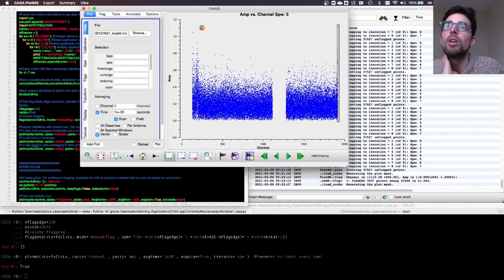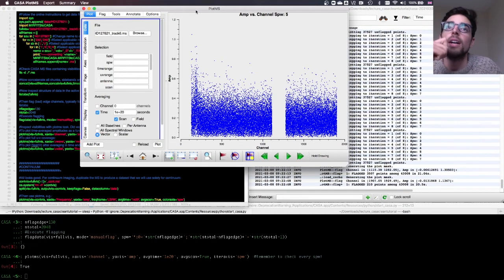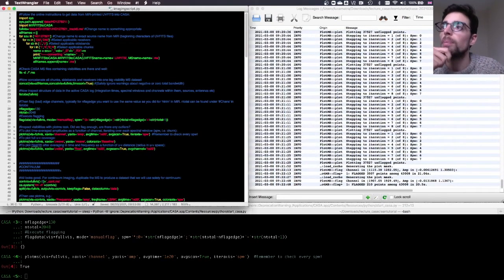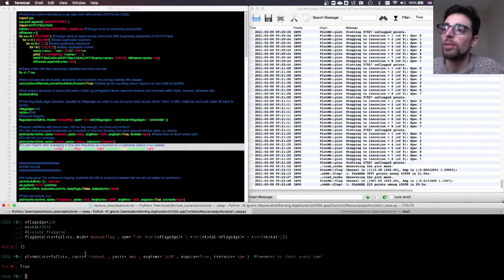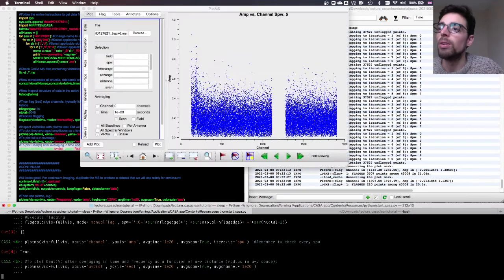Now, the next thing we're going to do is use plot_ms, but to plot something that we've seen in my non-imaging analysis lecture. We're going to close this now. We're going to plot using plot_ms. Now, instead of amplitude versus channel, here we're going to plot the real part of the visibilities as a function of UV distance. So that's again the radial plot in UV space that I talked about in my non-imaging lecture. Okay, so here we go.